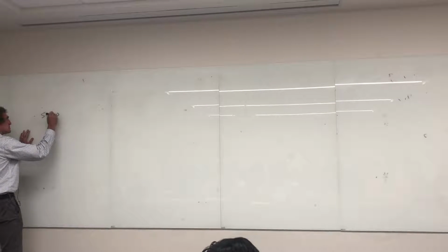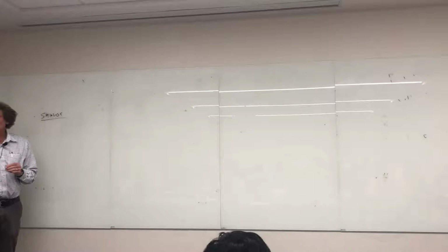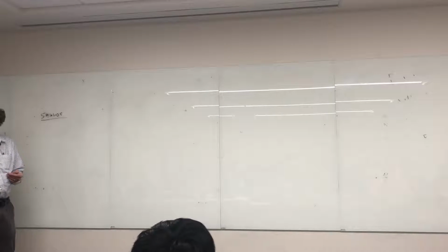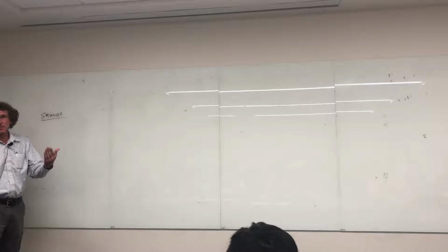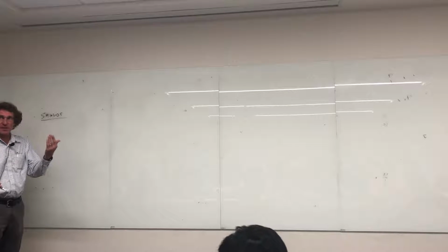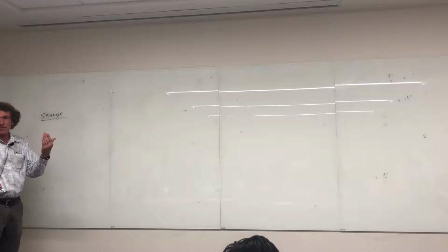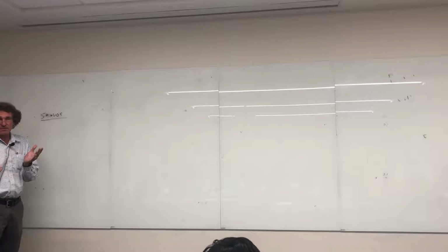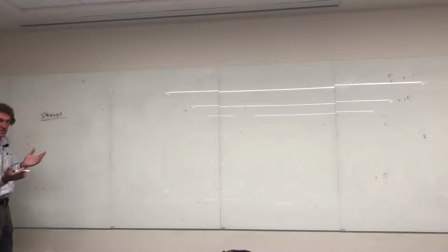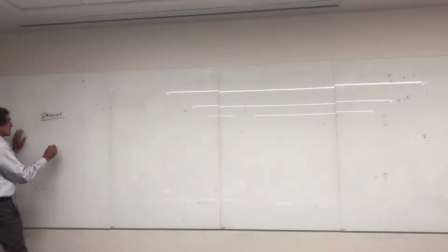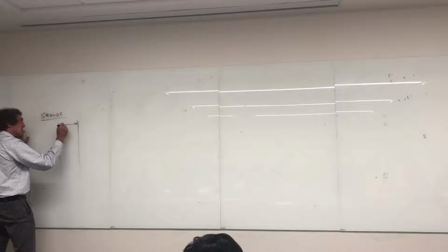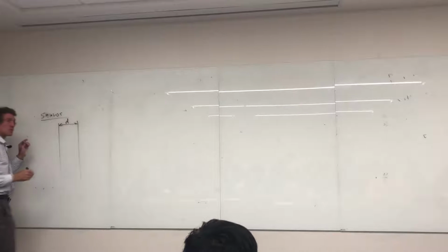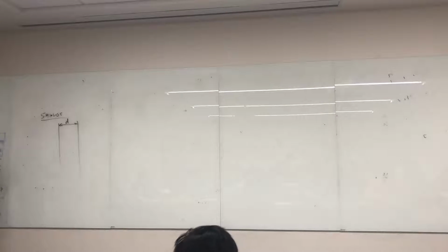So this is going to be shields again, and we'll start with planar shields. When I talk about a shield in general, it's to prevent signal from passing from one domain to another. Normally you want to prevent things from getting into sensitive equipment, or if it's FCC regs, you're trying to prevent things from getting outside of a noisy environment that would violate the Federal Communications Commission standards. So we start with a planar shield, and in general, I did this last time, if the shield has a certain thickness, I'm going to use the thickness as D. In the book, Wentworth uses T. I prefer D for a reason.